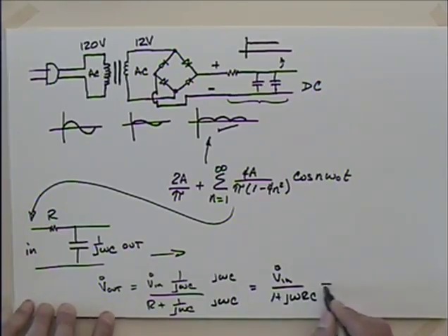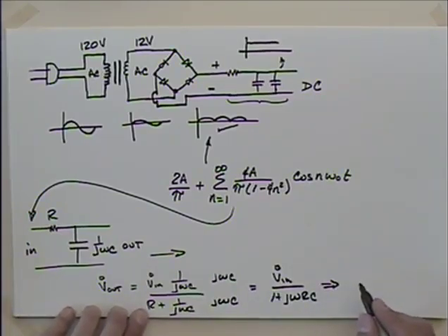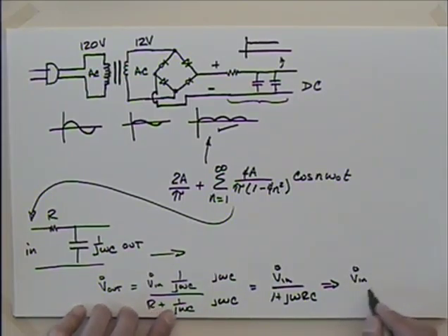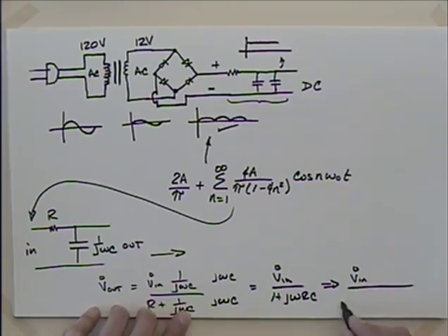So we could then put this into magnitude angle form. Whatever you get for your input voltage, the magnitude in the top is 1, so I don't need to worry about that. Magnitude in the bottom is going to be what? The square root of 1 plus (n omega naught RC) squared. So I changed out this omega here for n omega naught.